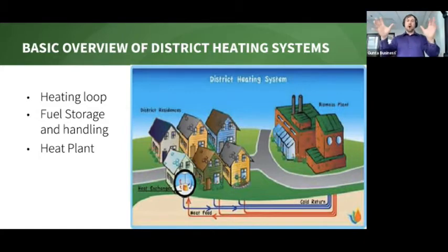How we typically design these things is that we have a number of heating units all working together efficiently, heating a water tank. Then it's ultra efficient, just water pumps and thermostats in homes calling for the heat, with the pumps circulating the water from the tank's reservoir of hot water. So that's the overview. The heating loop is a huge cost, obviously, because you need to dig and you need infrastructure to dig. The pipes are quite insulated, and you need a return and a flow line all in one. So that's all buried.